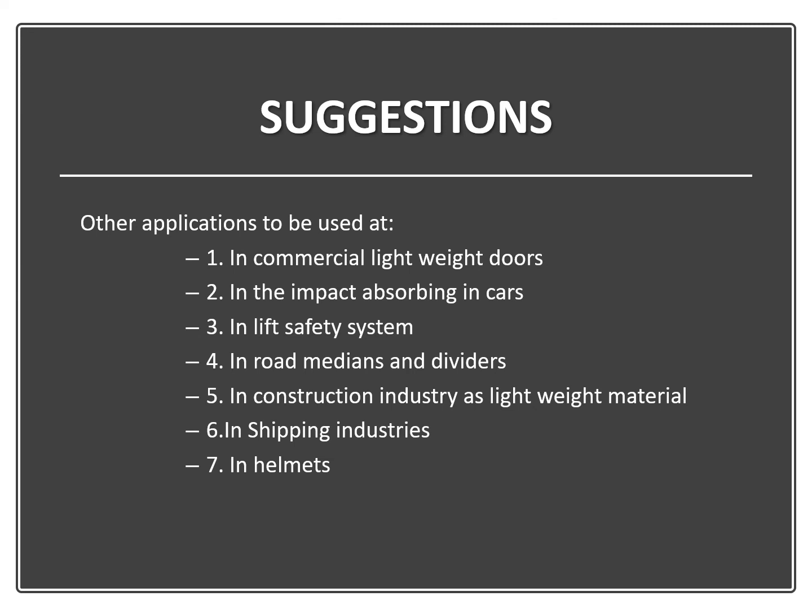Now I'll be talking about some suggestions that metal foam can be used for. As we know, metal foams haven't been widely used, but here are some applications we can use them in. First, in commercial lightweight doors. In impact absorbing in cars. In lift safety systems. In road medians and dividers. In the construction industry as a lightweight material. In shipping industries. Last but not least, in helmets.